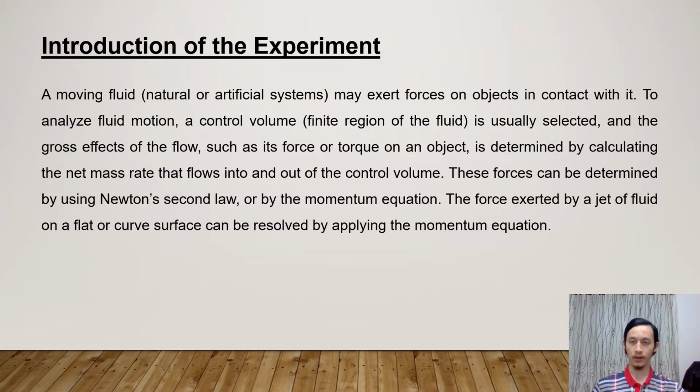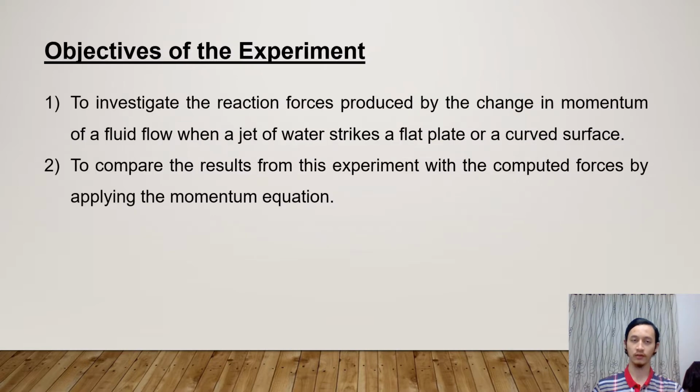The force exerted by a jet of fluid on a flat or curved surface can be resolved by applying the momentum equation. The objectives of the experiment. Firstly, to investigate the reaction forces produced by the change in momentum of a fluid flow when a jet of water strikes a flat plate or a curved surface. Secondly, to compare the results from this experiment with the computed forces by applying the momentum equation.